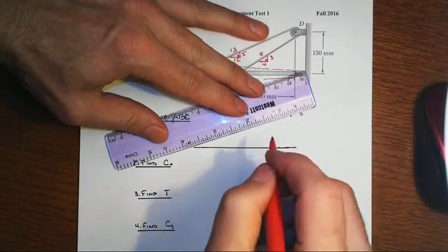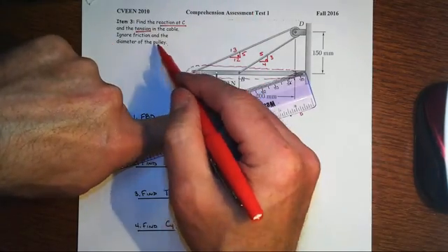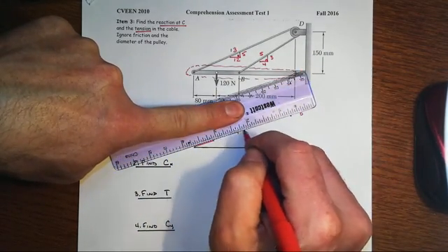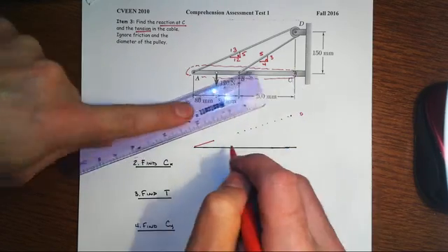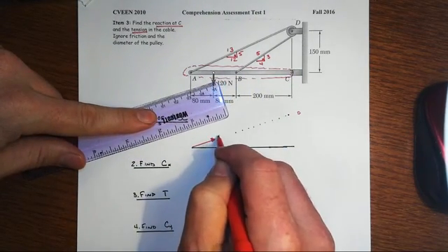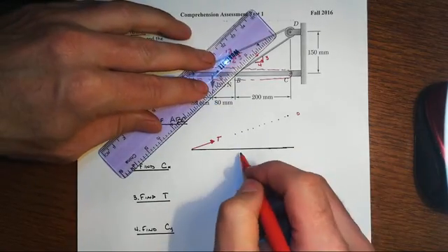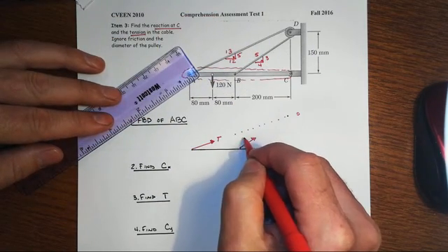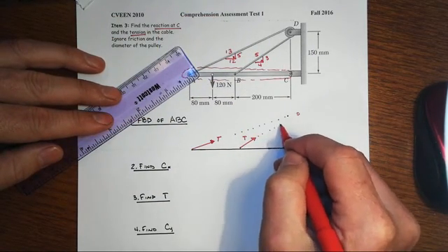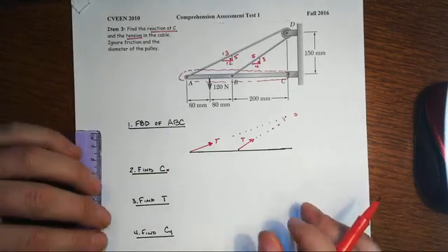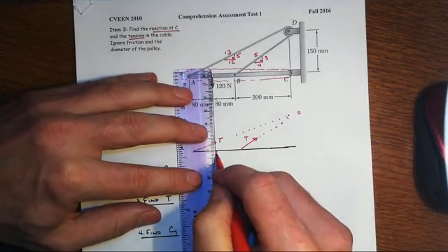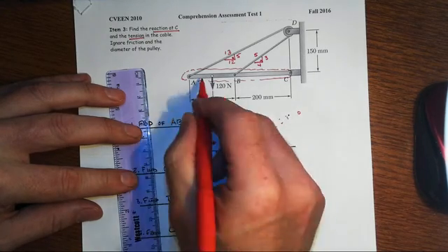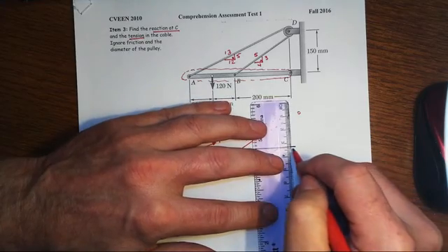So here's point D, where we're going to ignore the friction and the diameter of the pulley, so that means the cable will head along its line of action right towards D. And since there's only one cable, that's going to be a value T. Then here at this attachment point at B, we'll have the same thing: the same magnitude of the cable force, though it does have a different line of action there. We've got the applied force of 120 newtons between A and B, and then we've got the